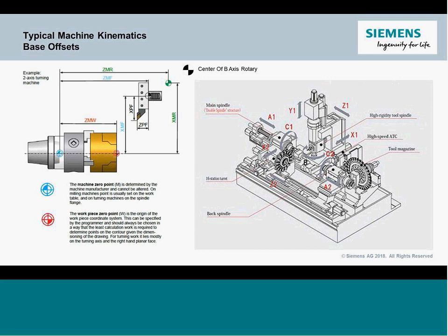Now, how is it configured differently than a standard traditional lathe with a normal traditional style turret? This is where the reference kind of comes from. So the main is all going to be referenced from the spindle. This is a pretty common commissioning method when you get to this advanced technology. So on a main sub-spindle machine with a more traditional turret, or a B-axis lathe, everything is referenced off the primary spindle face.